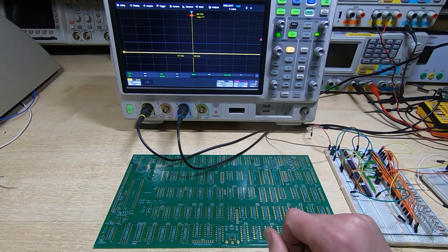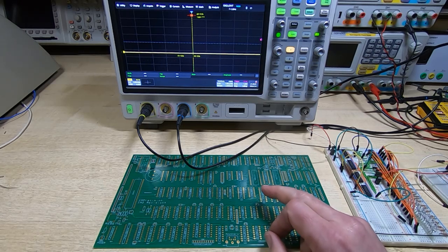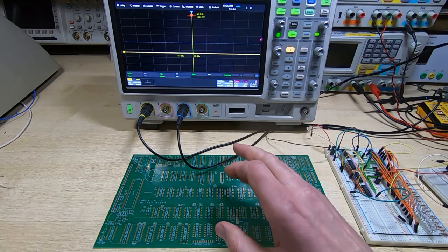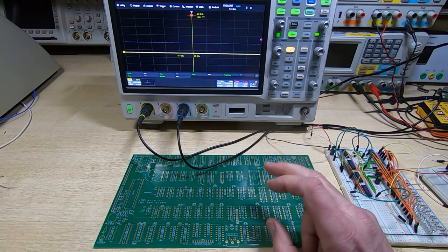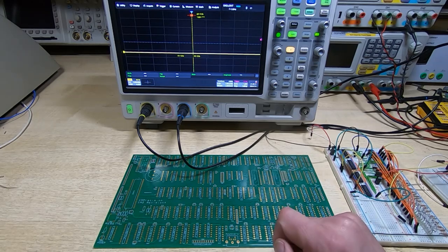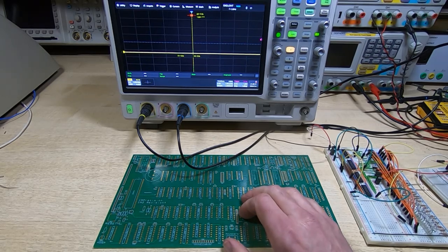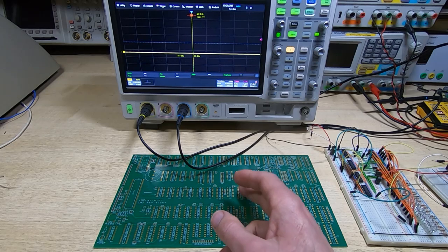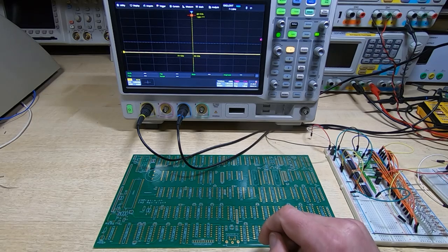But it's not as straightforward as it may sound, because the address bus is not particularly complex to drive, but it does need to be able to be tri-stated if I'm going to use DMA, because obviously the address bus has to be put into tri-state mode so the DMA circuits can use it. The data bus is a bit more complex because it's a bidirectional bus, and so you need to be able to control when it's feeding data onto the bus, when it's reading data back, and again it has to be tri-statable so that the DMA system will work.